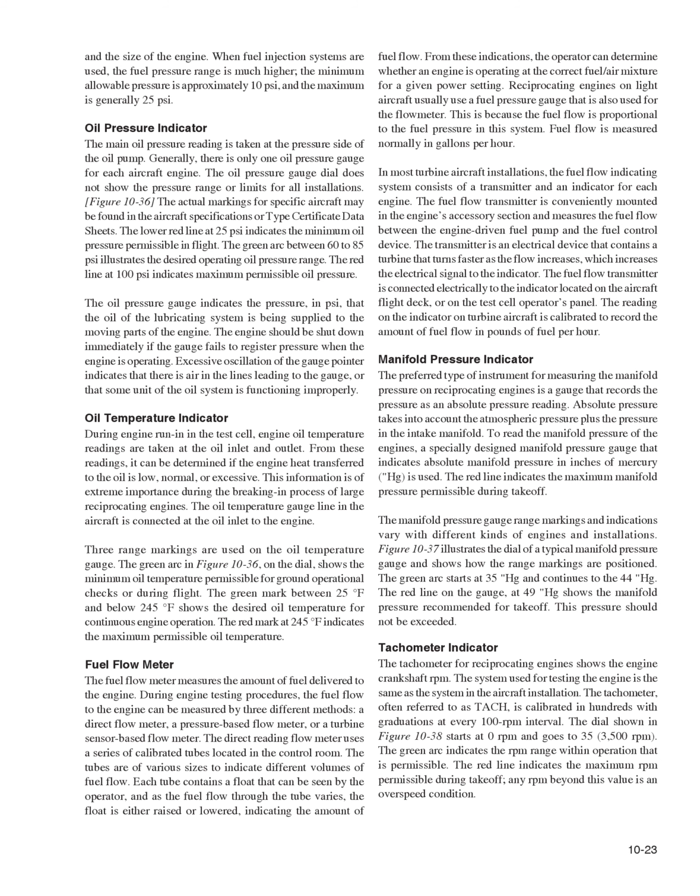Manifold pressure indicator. The preferred type of instrument for measuring the manifold pressure on reciprocating engines is a gauge that records the pressure as an absolute pressure reading.